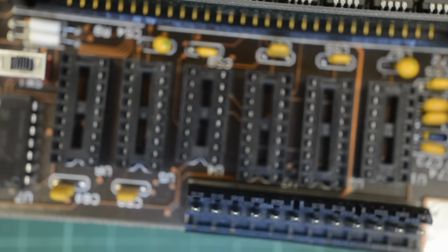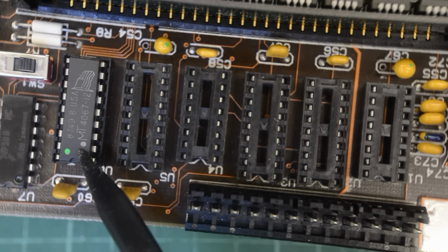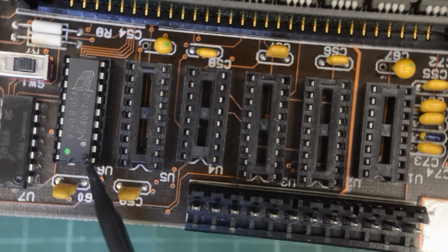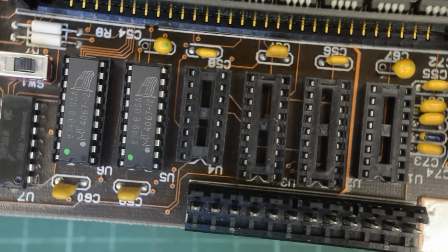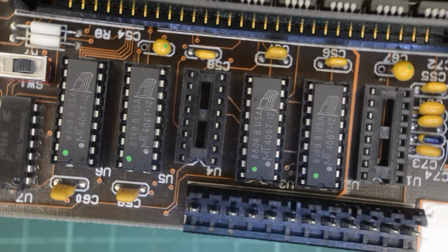Okay, so this is a mix of 41256s and 4064 chips. So let's replace those chips. I can hear you guys screaming, "Stop! These are empty branded chips." Well, I pulled them out of a working system. And just to make sure, they are also freshly tested in a Commodore shortboard. So they should be good enough, at least for this test. I will of course replace them later, because I want to make sure this isn't going to be a bottleneck when we overclock this machine later.